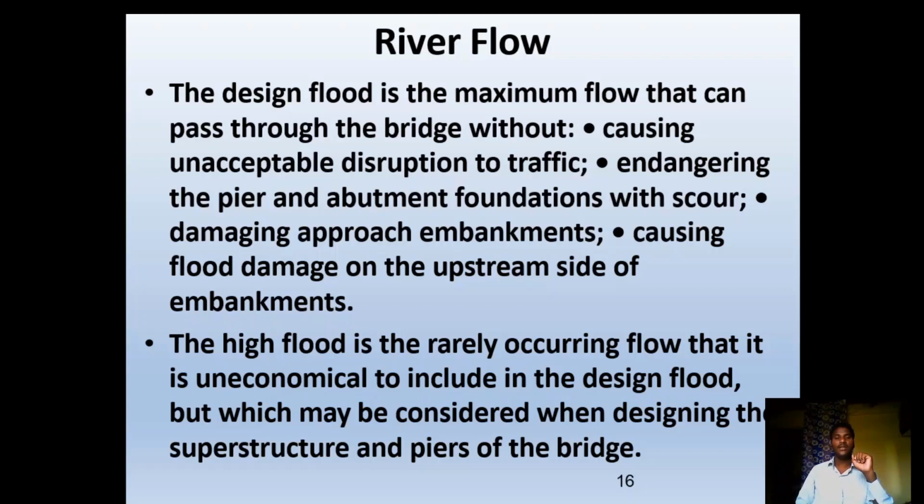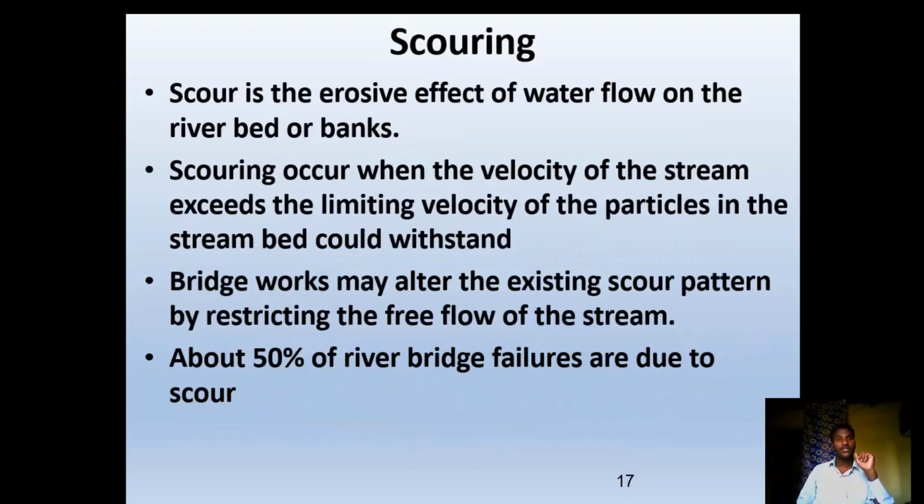The high flood is the rarely occurring flow that it is uneconomical to include in the design flood, but which may be considered when designing the superstructure and pier of the bridge. Scouring is the most important, once again most important factor.